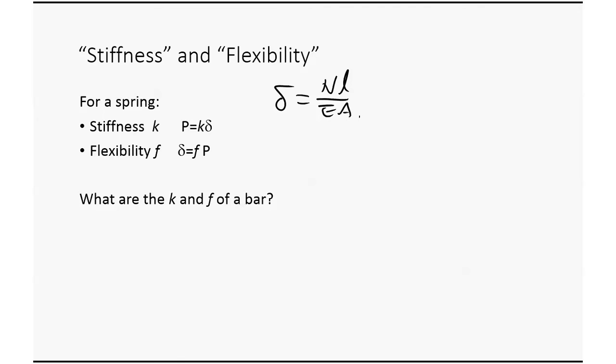It's a very stiff spring, right? What's a spring? You learned in physics. What's the definition of a spring? When you apply force, the force is proportional to the displacement, right? That's what we learn in physics. Now, for this equation, is the deformation proportional to the load, P, to load N there? Yeah, so it's a spring. It's a linear relation, so it's a spring.